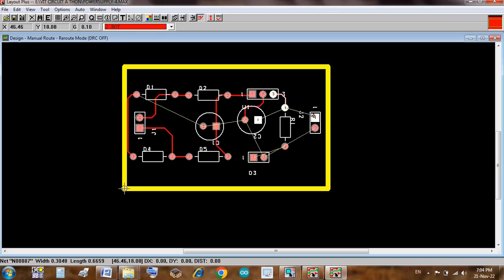See, the basic feature of Orcad is, you can see here, the traces are connecting between these capacitor as well as the regulator along with the resistor. So it gets highlighted at 3 junctions. It means you can route with terminal of R1 either, or with the third pin of regulator, or with the first pin of capacitor. So this will be helpful for you when you do the complex routing with more than 50 nodes or 60 nodes. Have in mind.